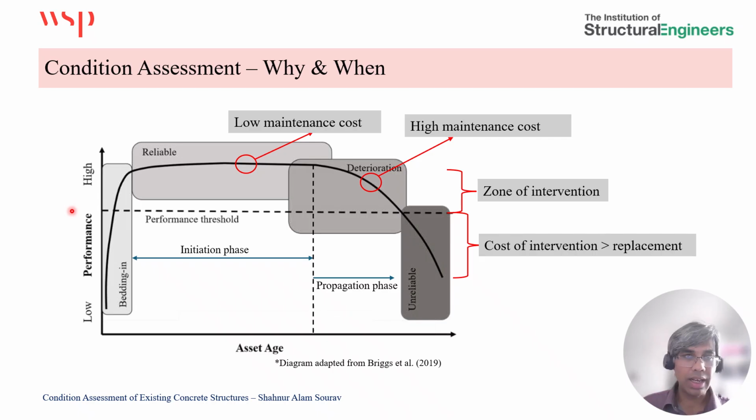So this is the slide. I'll talk about the performance and the overall maintenance cost as the structure ages with time. So in the beginning, we expect the performance of the structures to be high, obviously above the performance threshold. As the structure is in service, the structure will undergo the process of deterioration. During the initiation phase, this deterioration will be minimal, and at this stage, the maintenance cost will be minimal also.